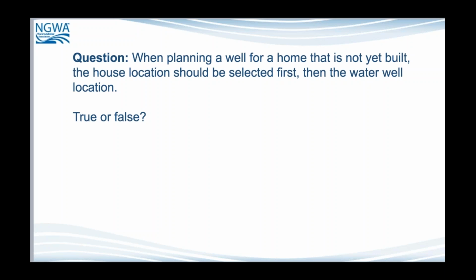We also talked about that most practices want that water well to be above ground. They're terminated above ground, meaning that the casing itself comes above ground. A lot of people like to think that they can terminate that casing or cap that well at ground level and put a driveway over it or put something around it and then they can access it, or try to put it into a pit. That used to be the way it was done a long time ago. It is no longer the accepted practice.